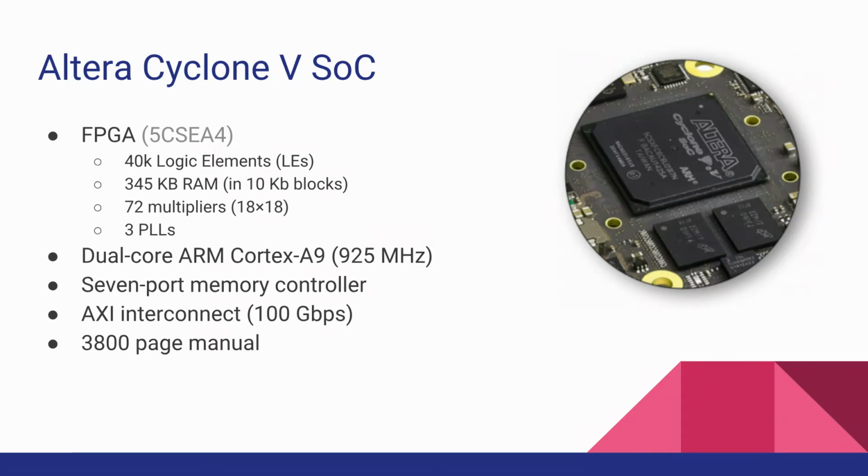So zooming in on the chip, on the FPGA chip itself, it's got 40,000 of these tiny little programmable things, which is quite a lot. Like I said earlier, you can do a 68,000 in under 10,000 of these things. So you can have 4 or 5 68,000s working in parallel, no problem. It's got RAM on board, which is great.